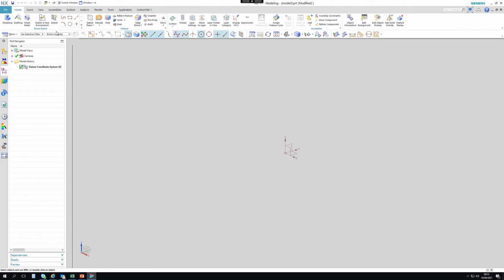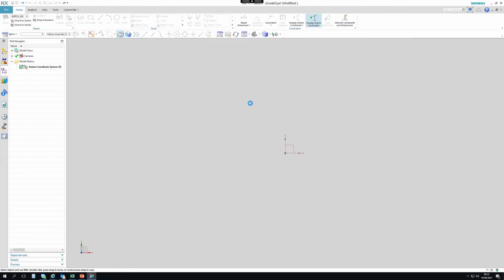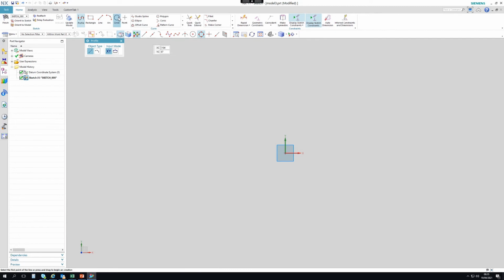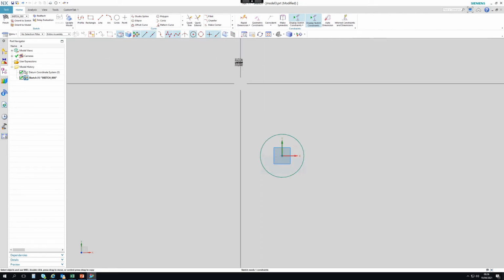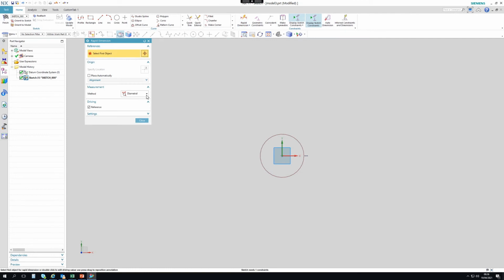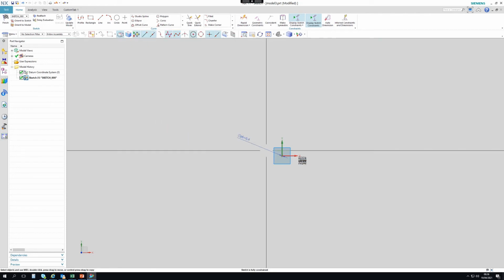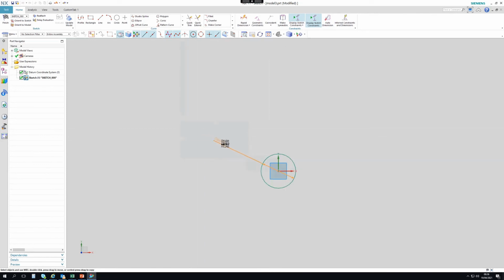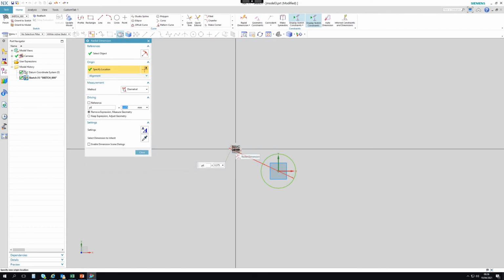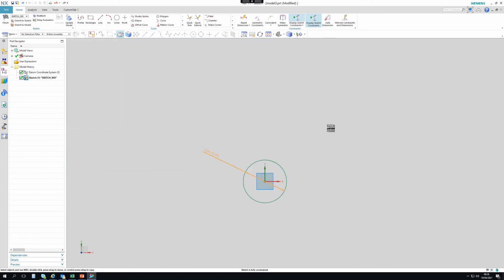Okay, so let's do a new part. Do a new sketch. Right, so let's draw a circle this time, but this time we're going to go for the 0.375. So this will be 0.375. Let's just divide it by 2. So that's the positional tolerance on both components.